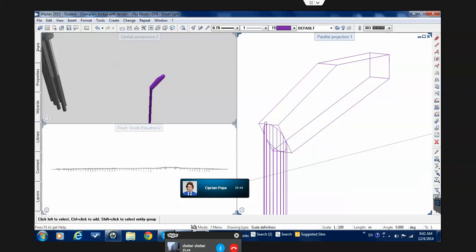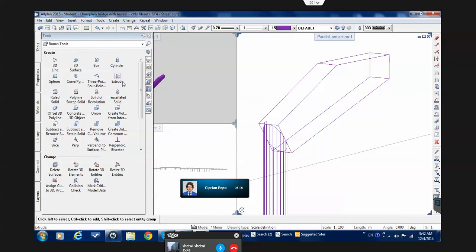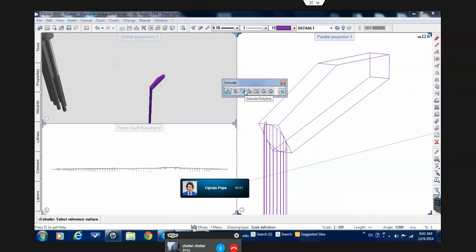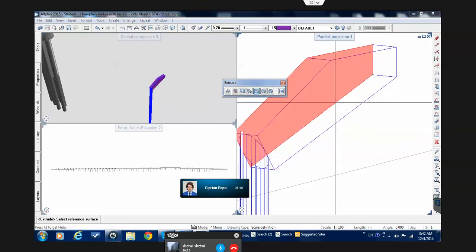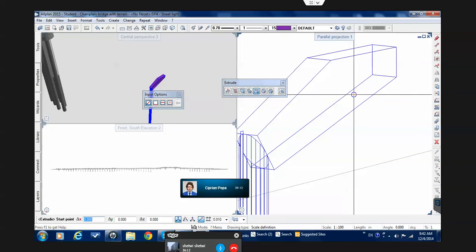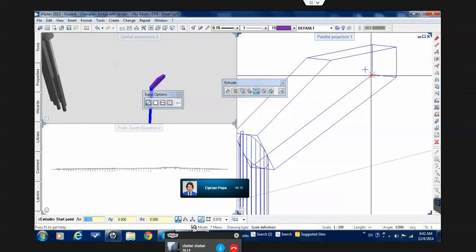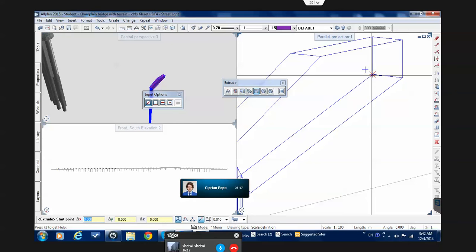Okay, we'll do just some extrusion the other way around, but I needed some referencing, so I'll go like this. I'm going to extrude a polyline. Let me deactivate the rotation. I'd like a polyline, not exactly this surface, a smaller rectangle on this surface. And I'll need to use some relative coordinates for this.